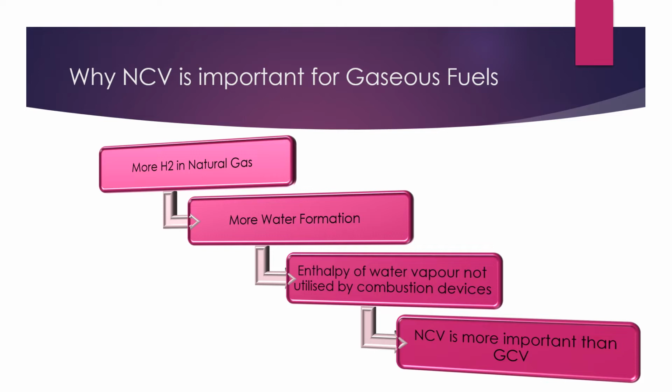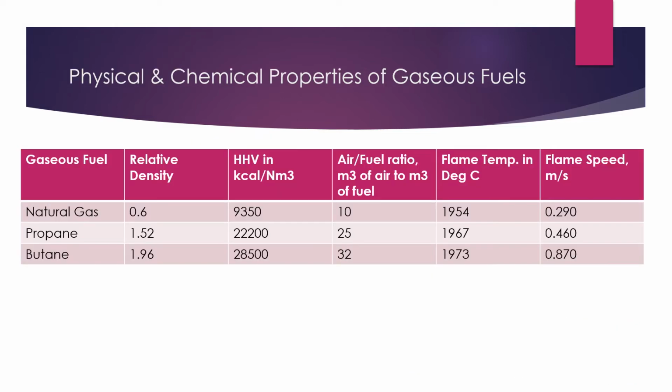Gas combustion devices used for combustion of gaseous fuels like natural gas do not utilize the heat content of water vapor. So gross calorific value is of no importance in case of gaseous fuel. Hence, gaseous fuels are compared based on net calorific value.